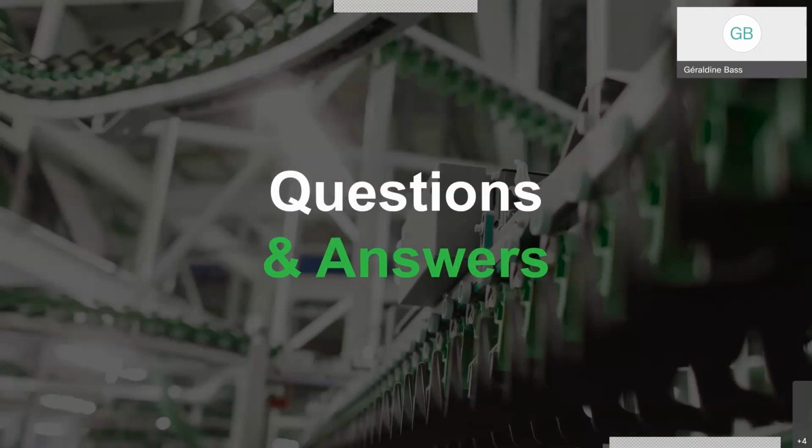So the first one, there is a question about the standard. Is the standard 61439 affecting the calculations on ProClima web? Yes, yes. In fact, ProClima web considers one part of the 61439, which is the IEC 890, that calculates the surface dissipation of the enclosure. So on every calculation, it is calculated according to the position that is declared. Imagine if it's in front of the wall, so the rear part of the wall cannot dissipate, okay? So it doesn't dissipate.